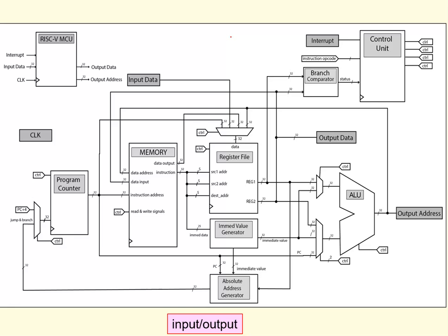Last thing here is input and output, and I think it's not really a module, but we're just kind of pretending like it is a module. It usually appears like a box in any diagram, but we don't really have anything like that here. So an input operation would be something like a load operation. We'll just say 0x20. Okay, so this right here for an input operation is going to be the port ID. This can be an offset if you use it. This is the register that you're putting the data into.